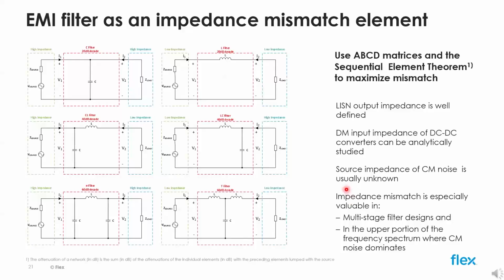When we define insertion loss, we said it's a power loss provided either by a real attenuation or by impedance mismatch. Attenuation is losses and mismatch is reflection. So, in a power processing filter, mismatch is more desirable than attenuation. And this is one reason why multi-stage filters are also more desirable. They offer more flexibility in introducing mismatch and are more suitable to the high noise amplitudes that are typical in high power applications.